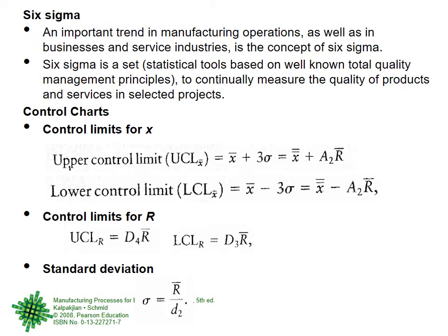And you can find the mean from each sample of 10 pieces and the standard deviation. Now they found out this unbelievable thing, that if you put the tolerances as X bar plus 3 sigma and X bar minus 3 sigma, then 99% of the pieces will be within the tolerance. Less than 1% will fail, for example.